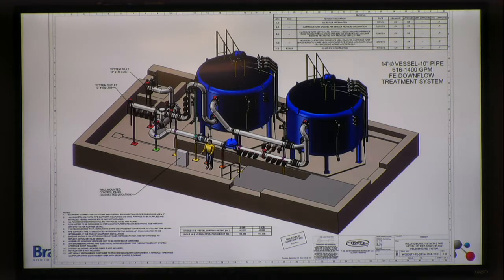So you wouldn't want to take well 6 down? Because I don't know if it's like 6, 5, 6. Well, 6 is in that 5 to 7 range of picocuries per liter. Yeah. So the idea here is, let's utilize this in its most efficient manner with the water that has the highest radium, enabling the water that comes from that to essentially be very low levels of radium. I was going to say radium free, but I won't go there. It's very low levels of radium. It essentially acts as a dilution for well number 6.